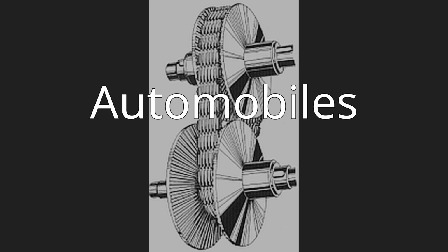Applications. Automobiles. The first mass production car to use a CVT was the 1958 DAF 600 from the Netherlands. Its Variomatic transmission was used in several vehicles built by DAF and Volvo until the 1980s. The 1987 second-generation Ford Fiesta and first-generation Fiat Uno became the first cars to be equipped with steel-belted CVT, as opposed to the less robust rubber-belted DAF design. The 1999 Nissan Cedric used a toroidal CVT, unlike the pulley-based designs used by other manufacturers, marketed as the Nissan X-Trail, which incorporated a torque converter. Nissan then switched from toroidal to pulley-based CVT in 2003.